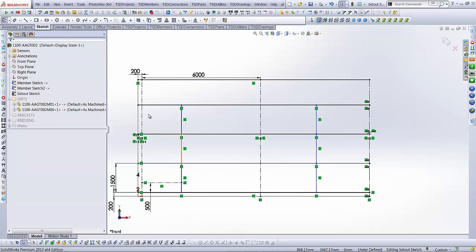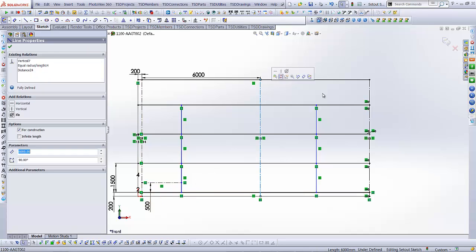And what I also can do, now you'll notice with my driving sketch I've actually got column center lines here, which I will snap on to the columns driving sketch, or the driving sketch at the beginning that we modified, and then that sets up the center so that if I was to change a bay, the whole lot would automatically update.